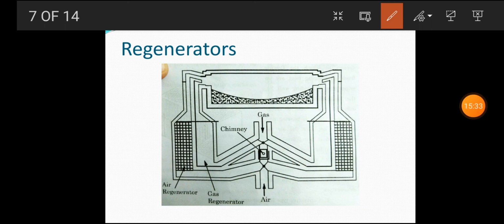So as in this figure, it shows the application of a regenerator as heat recovery from ventilation. Certain factors such as reversal time and area of storage decide the material and size of the brick. If the reversal time is long, it will lower the average temperature and lead to loss of heat also. Consequently, it reduces fuel economy.